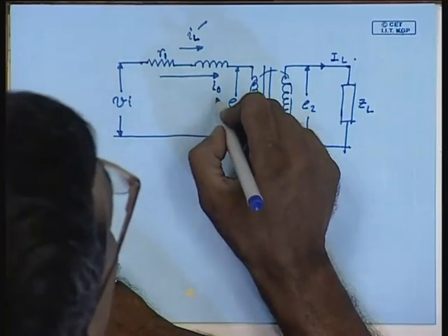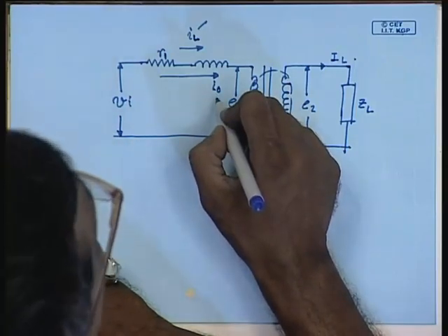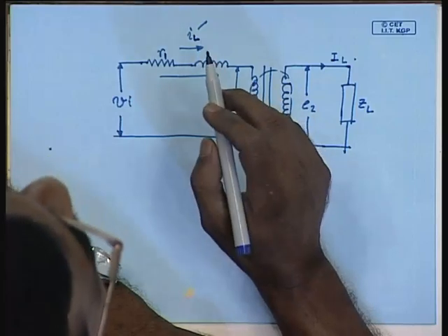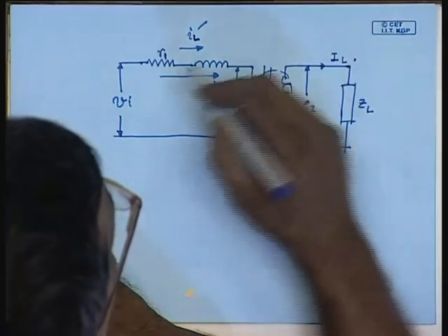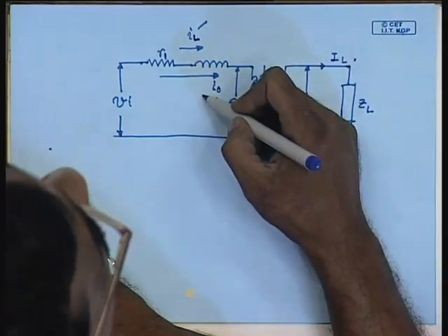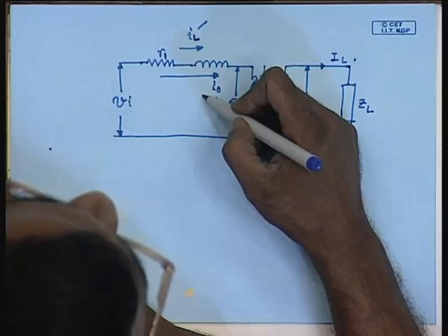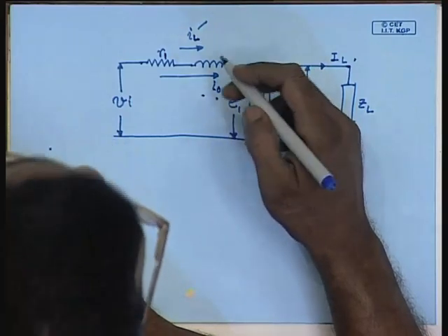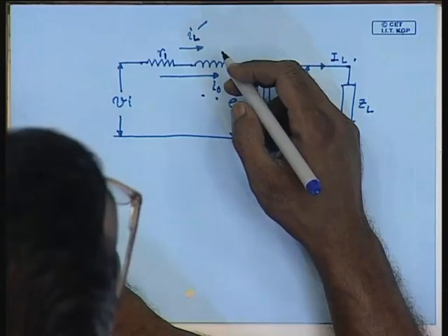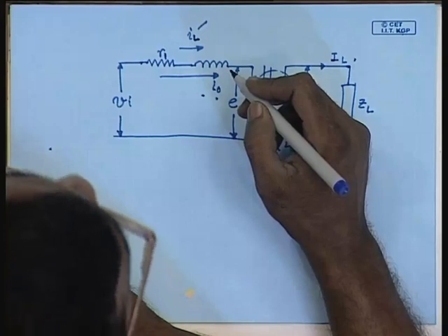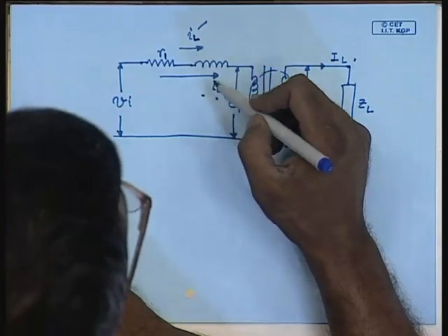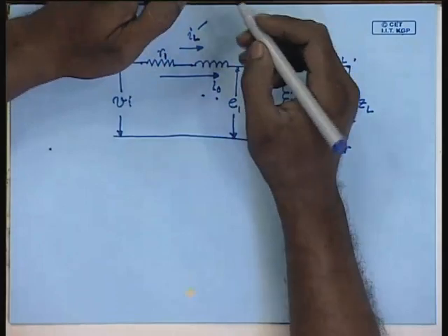Now, I0 is much smaller compared to IL dash in a normal transformer. So, when a transformer is loaded, IL dash will dominate over I0, therefore, the waveform will look very much sinusoidal, and although there will be harmonics of the magnetization current present, it will not be apparent since the magnetization current constitutes only a very small fraction of the total current of the transformer.